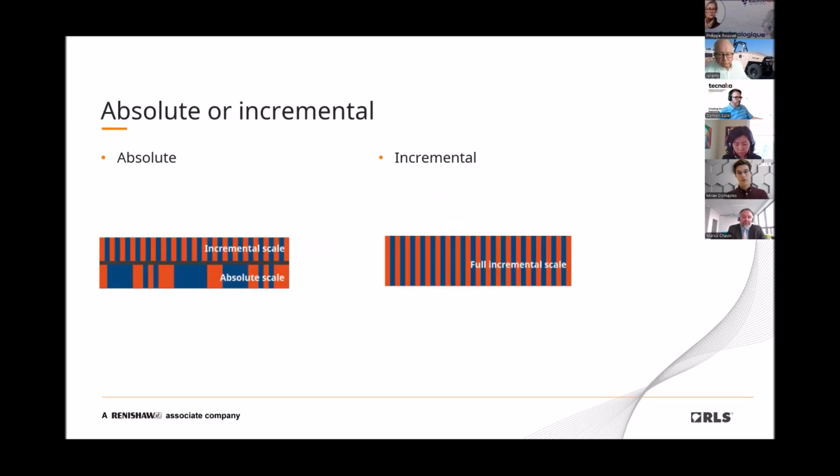With this, we move on to the dilemma of choosing whether an absolute or incremental encoder. And encoders tell position similar to how we tell time. We can say it's exactly 5:25 p.m. by looking at a clock, or using a stopwatch, we can say exactly 5 minutes have passed since we started this exercise. So an absolute encoder can be compared to a clock because it reads the unique position, some pattern of a scale, in our case a ring, and therefore knows the absolute position.